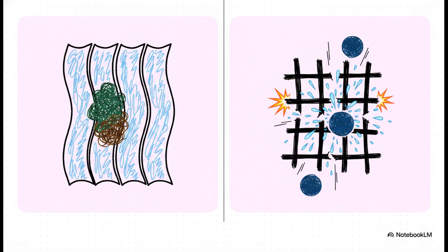So, below those nozzles, the water hits the fill. That's the core packing material of the tower. Facilities basically have to choose between 2 main types here. On the left, we have film fill. This stuff spreads the water out into these highly efficient, ultra-thin films, which maximizes the surface area. Super efficient, right? But if your water quality is bad, it clogs up incredibly fast.